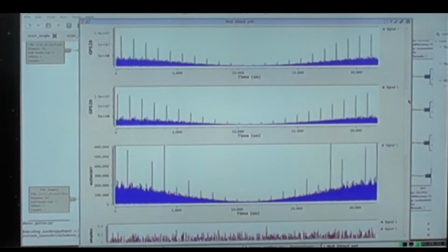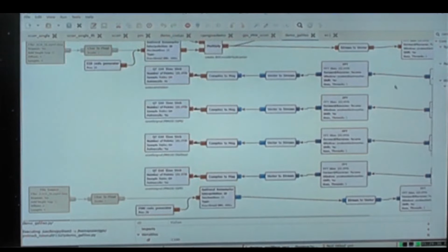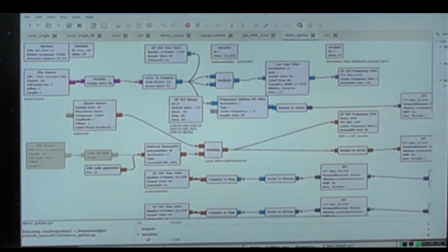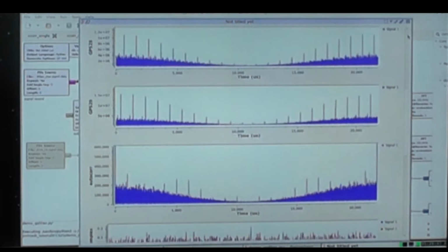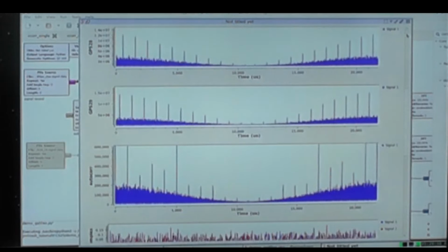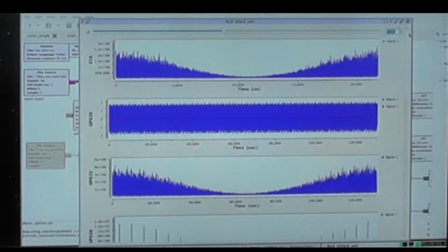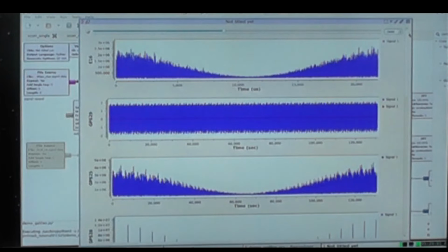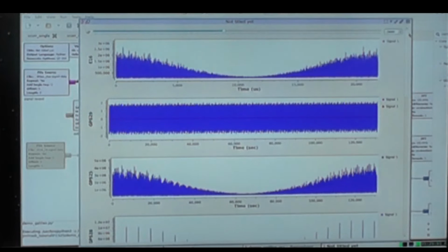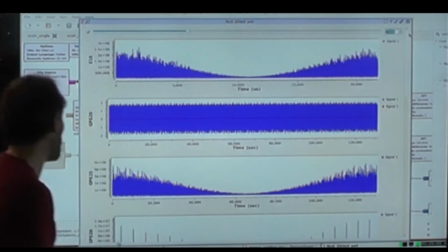Now, because I prepared the lab session, I can also tell you that there is another satellite that will appear at 3.6 kilohertz. So let's have a quick look at what happens if I shift my local oscillator by 3.6 kilohertz. If you go here on the top and you replace 1.1 kilohertz with 3.6 kilohertz, it is a bit computation intensive. So it does take a bit of time to refresh, but you should see GPS 25 come out, hopefully.